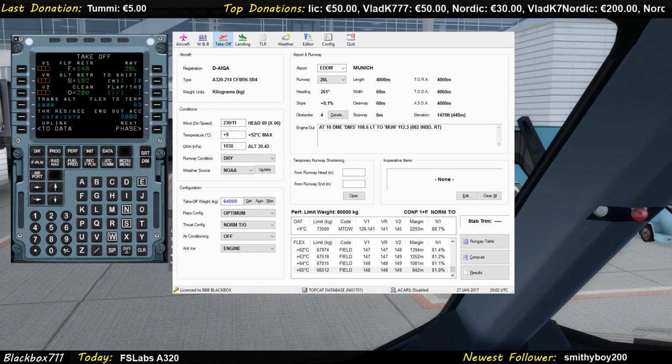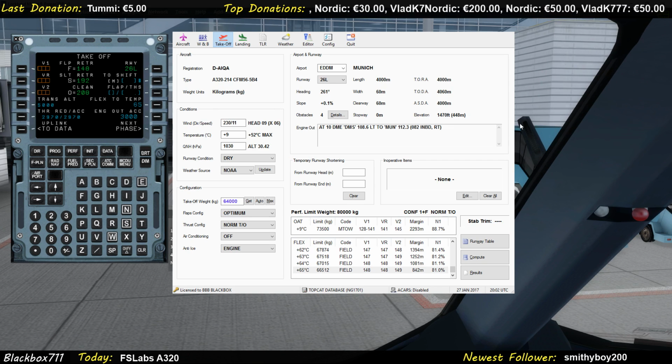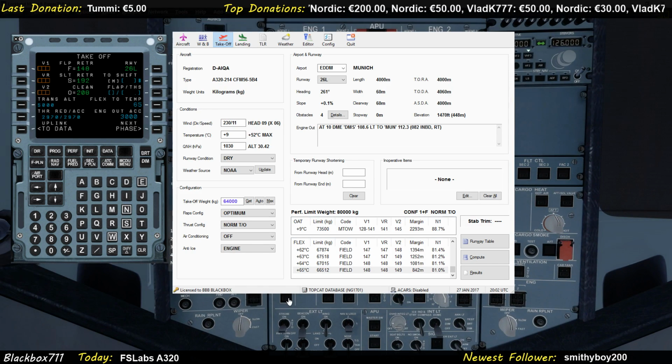on this probe here. Very simple mechanics. Just a little pointy probe here between the windshields. When ice accumulates on this pointer, then you pretty much know that there will be ice on the leading edges of your wings. So that would be the latest point to switch on the wing anti-ice.